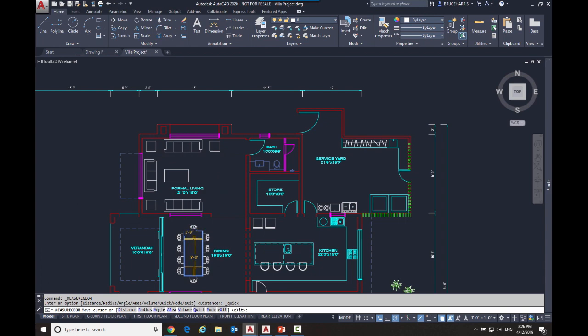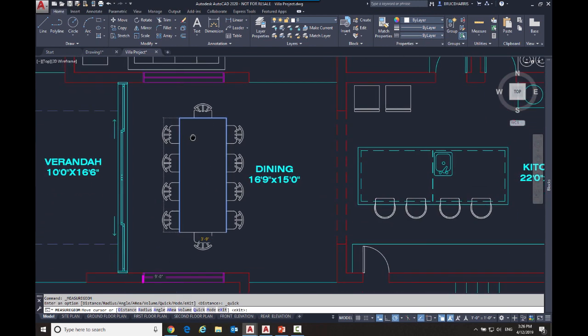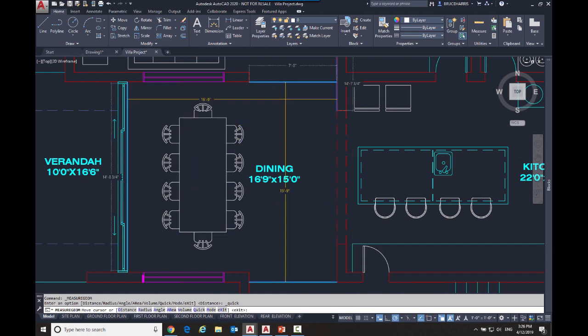And obviously it depends on how the geometry is drawn. Now when you see it put these little L shapes in the corners like you're seeing here, that's telling you what it sees at 90-degree angles. So that's what it's giving you the dimensions of in this yellow dimensions. Now it's also giving you some other, as you can see, gray dimensions.